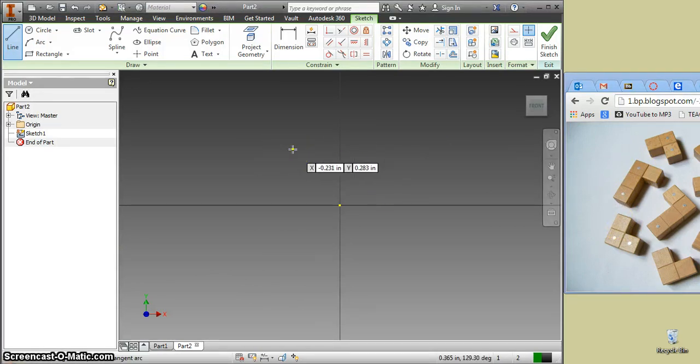It's very important to make sure that your lines are all straight. So you'll click and drag your mouse over. I like to line it up with my center point at the beginning, so it doesn't matter how long your line is, because we can change that using the dimension tool after. All you have to make sure is that you pay attention to the degree.